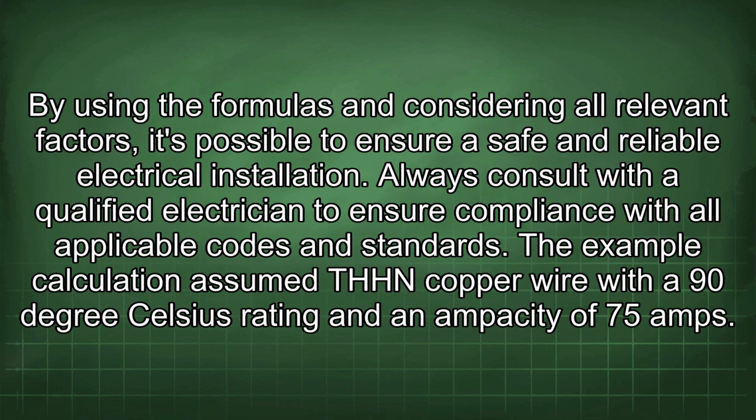By using the formulas and considering all relevant factors, it's possible to ensure a safe and reliable electrical installation. Always consult with a qualified electrician to ensure compliance with all applicable codes and standards. The example calculation assumed THHN copper wire with a 90 degrees Celsius rating and an ampacity of 75 amps.